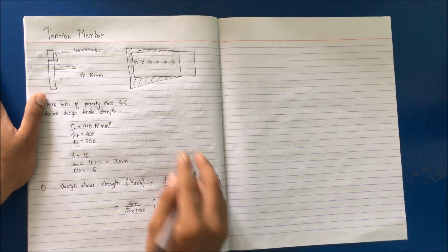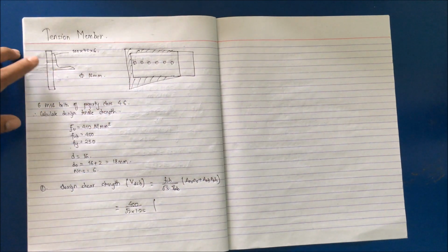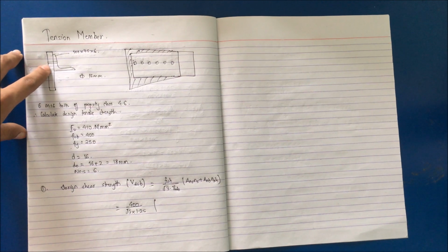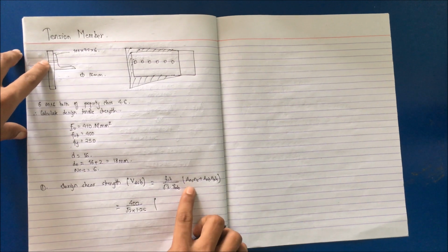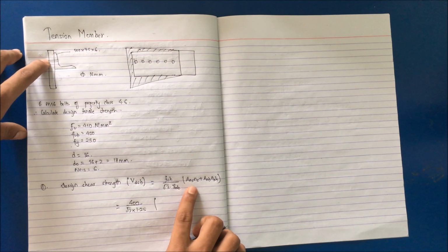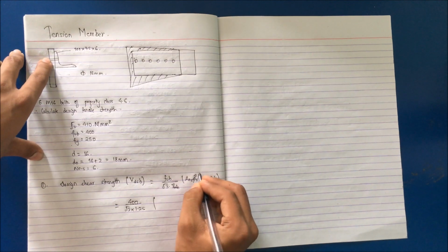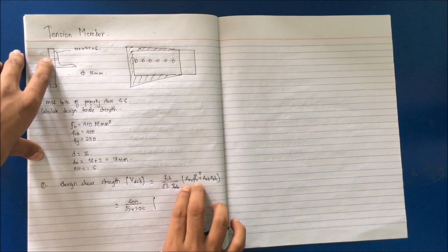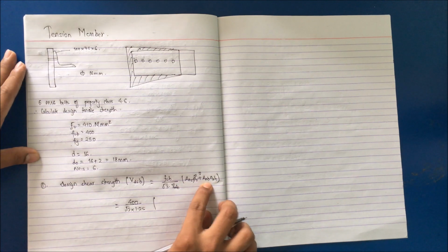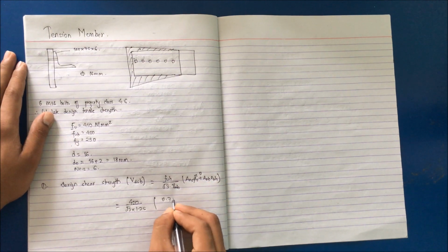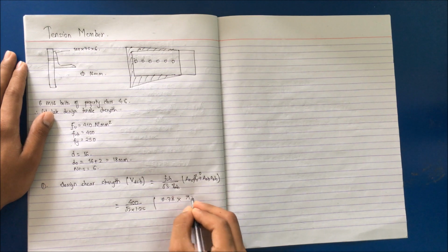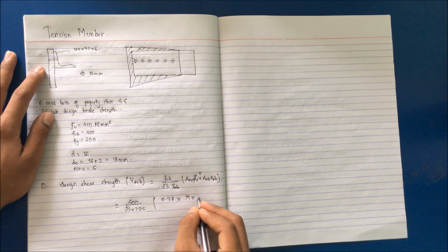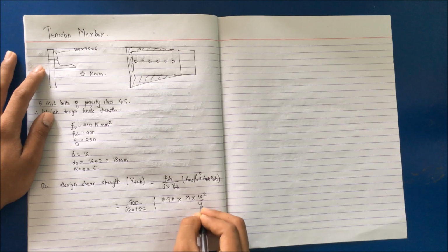ANS, this is a case where number of shear plane intercepting the thread is equal to 1. There is no intersection of the shank with the shear plane, so NS will be 0. Number of shear plane intercepting shank will be 0, so will be the total value here, and we'll consider this only, and we'll multiply it by 0.78 by the diameter of the threaded portion, d square by 4, so diameter is 16 square by 4.